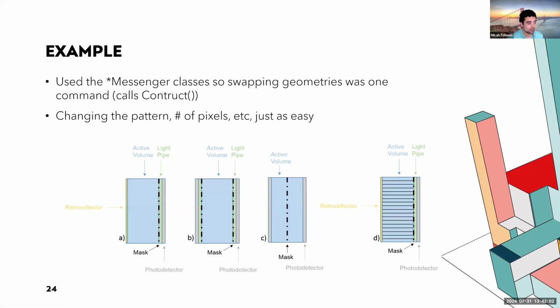So I was able to do this in Geant4. I defined functions to build these detectors and then was able to flip between them easily and collect all the tracks and events and feed that into our imaging algorithms and evaluate which one is performing best, what sort of resolution we're getting in light, photo detection efficiencies, things like that.